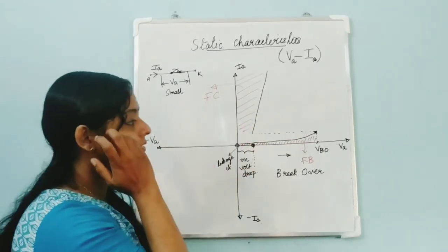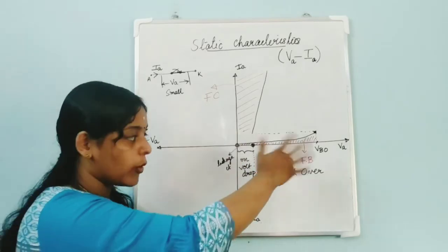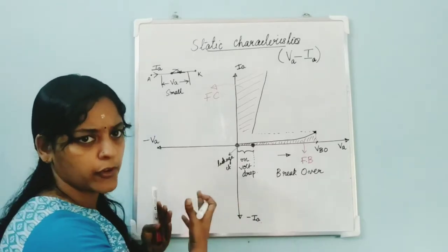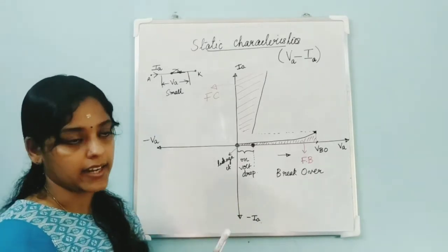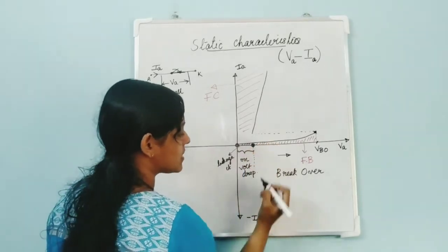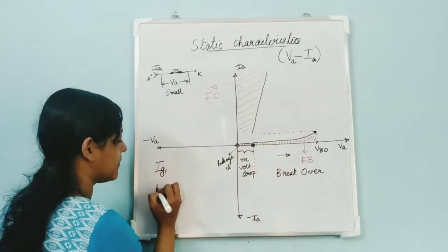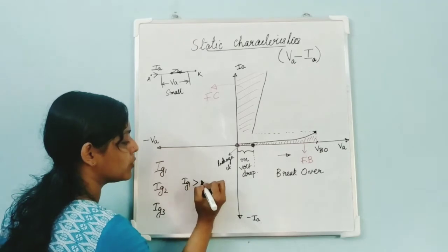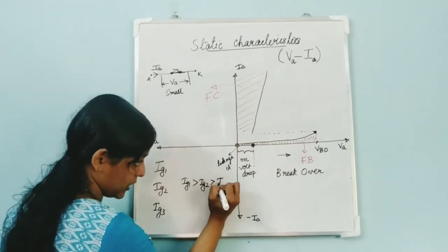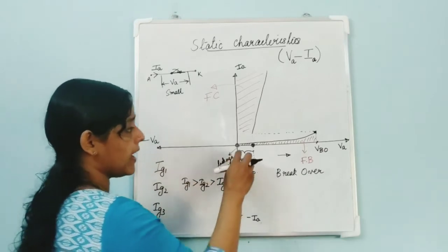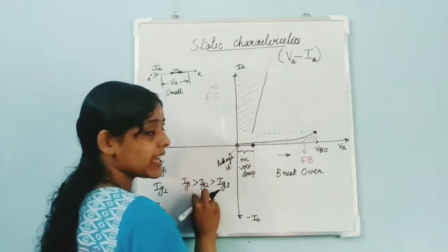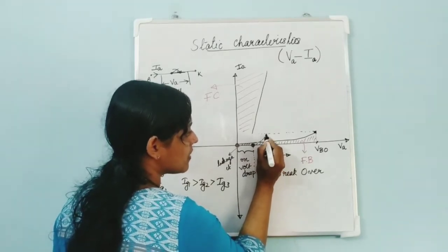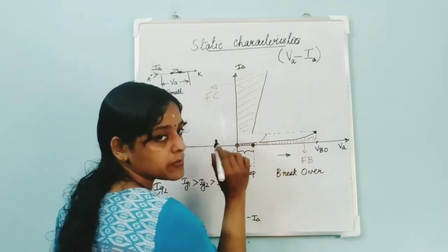Okay. So far we have discussed only the voltage. We didn't mention anything about the gate. Now you just remember what we discussed a few minutes before. Gate current, we have considered gate current, isn't it? We had the gate currents IG1, IG2 and IG3. And your IG1 was higher compared to IG2, which was higher compared to IG3. So when you increase the voltage and if I am applying a gate pulse, the device will get turned on at some point like this. Isn't it?